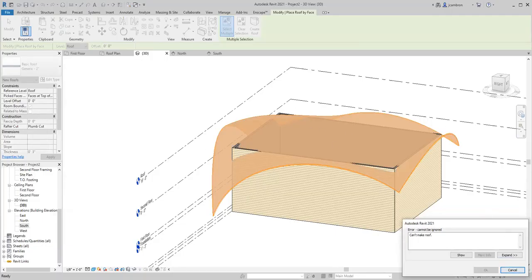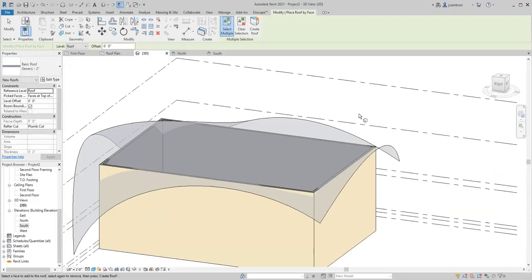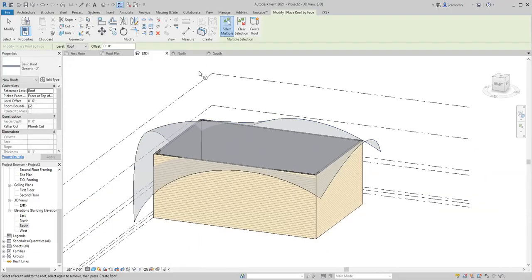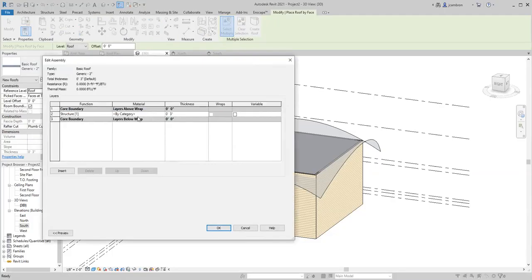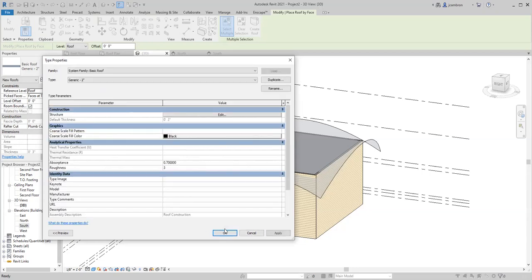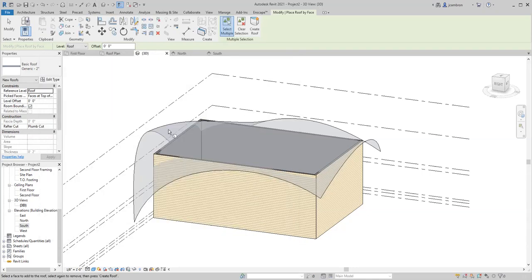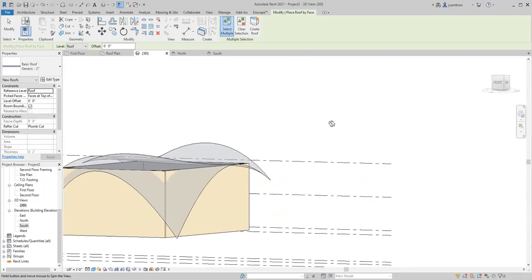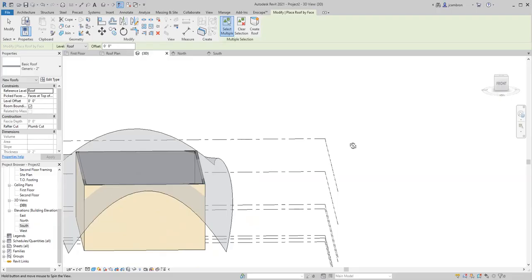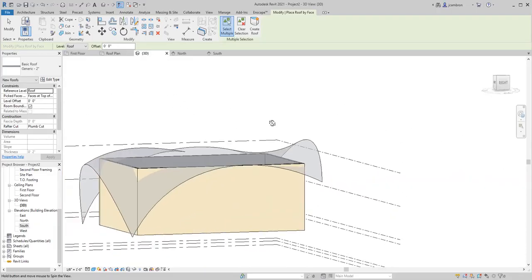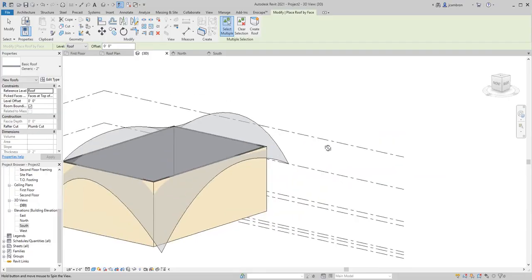I had played around with the same shape a little while ago, and I had no problems with it even at 8 inches. So, of course, when I'm giving presentations, that's when the problems arise, which is fine. So that means that the thickness of this can only be 2 inches. Now, you might think, well, Javier, who's ever going to do a roof that's 2 inches thick? Actually, complex curved roofs like this are typically going to be made out of concrete. So you do a concrete form, and 2 inches for something this complex is actually kind of common.